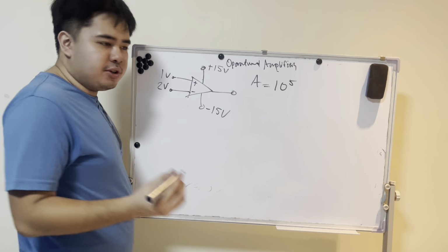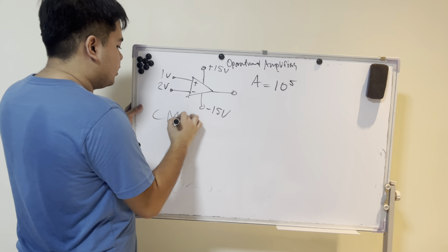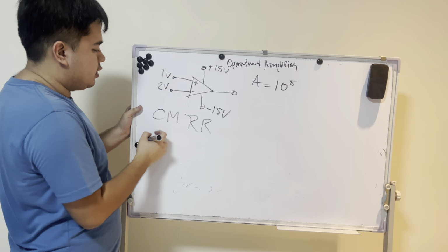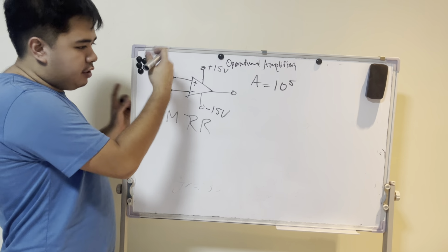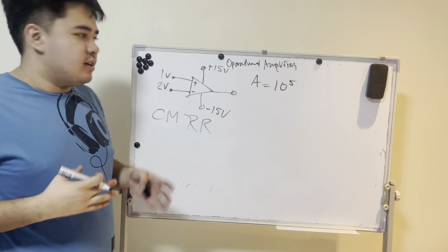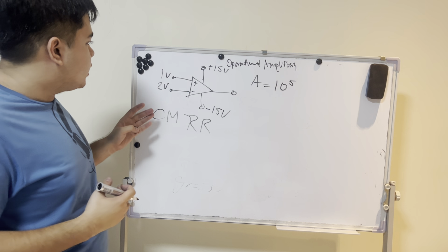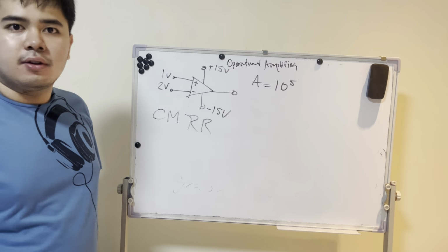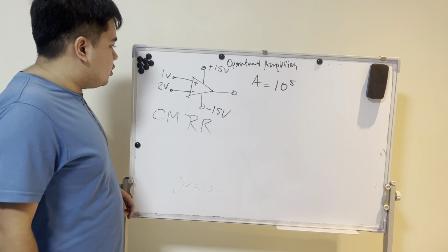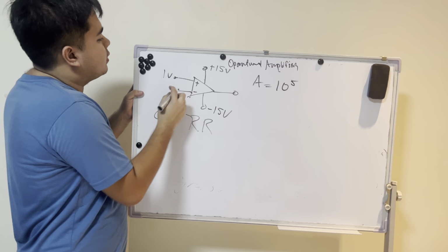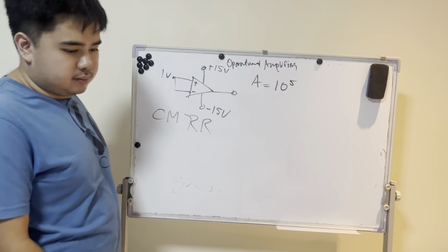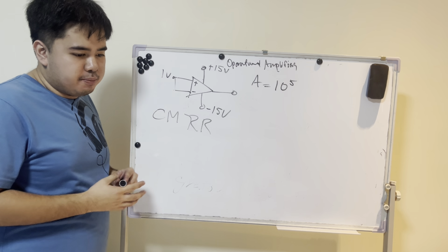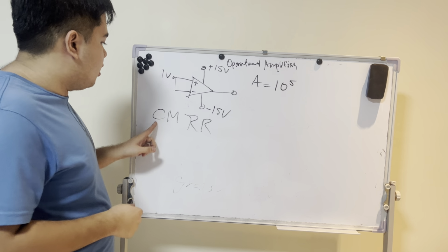First, we are going to discuss common mode rejection ratio. What is the common mode? What we have talked about so far is the differential mode. The differential mode takes the difference, multiplies it by the gain, and that's what comes out. The common mode is what happens when we connect them together. So when we connect both the inputs to one source, that is common mode.